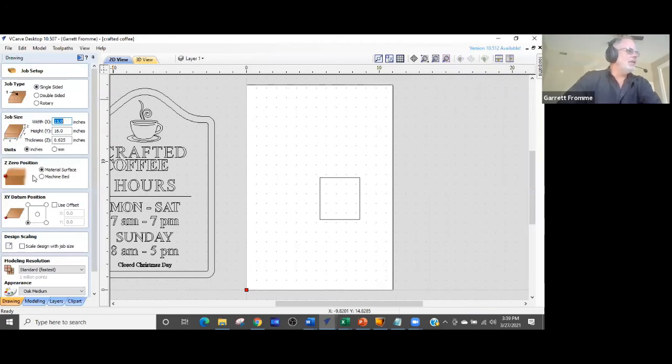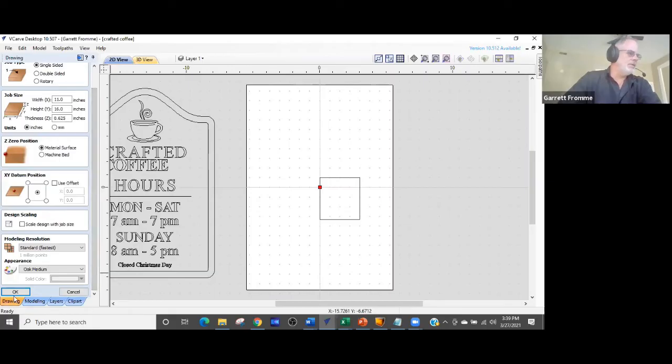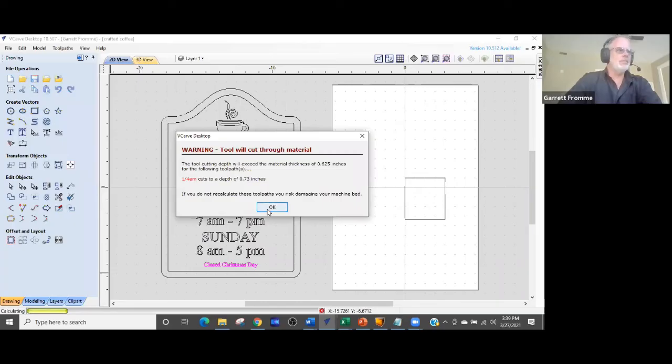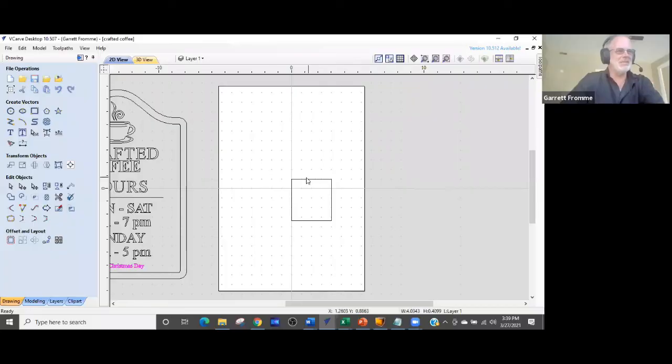It's easy to design off the center because most designs are based on center. It wanted to redo all my tool paths. That's why it kept giving me all those alarms. It's easier to design things off of the center. And then when you go set up your tool path, it's just easier to set up your X, Y 0 point and your Z 0 point on the corner of the material closest to the home position of the machine.